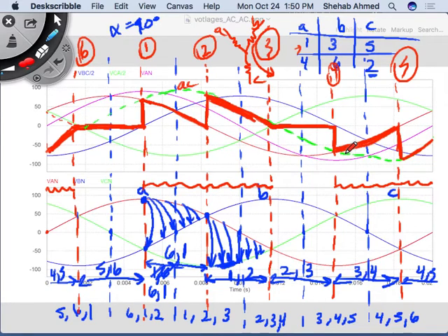Why do we want to obtain this waveform for three-phase? Because sometimes you don't want to put the full voltage across your three-phase load, like in motor starting. I'll talk about applications next after we finish the waveforms. Motor starting, light dimming, heater control, all of these are AC applications where you control the power through the heater, or limit the inrush current in the induction motor or the transformer, by starting with a small voltage and then increasing it.